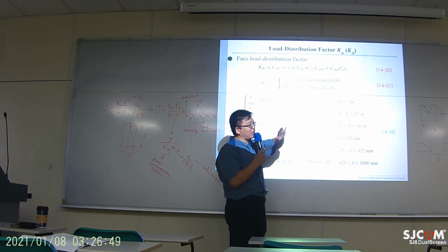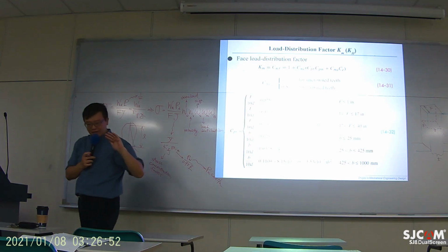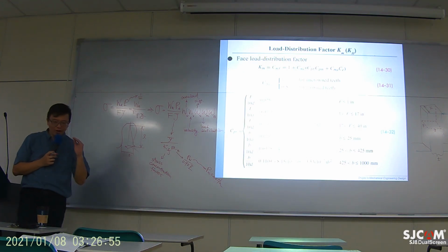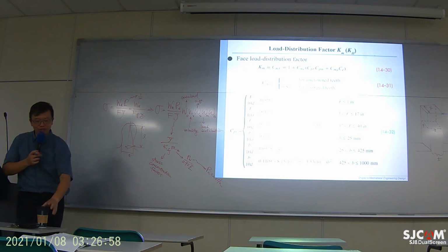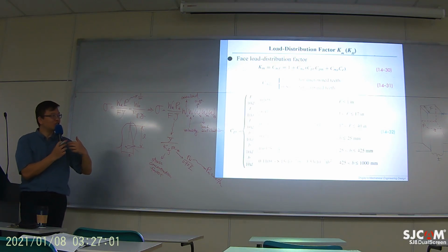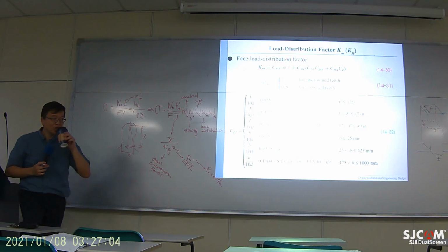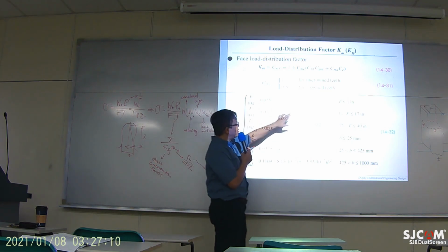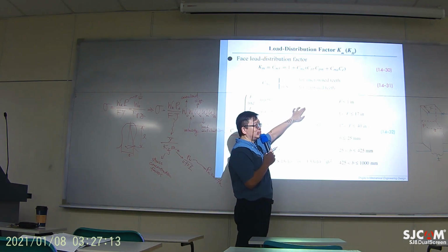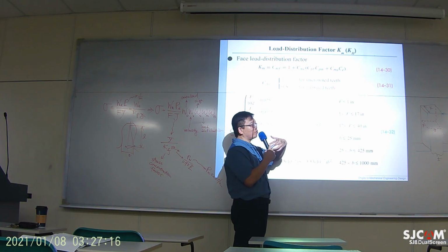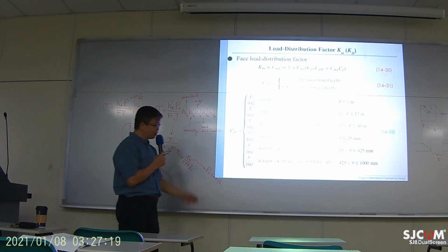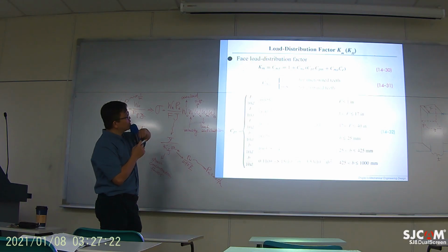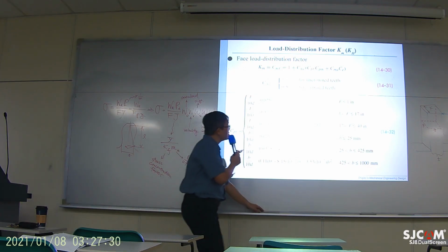Usually after machining, the edges of the gear teeth are sharper, so you kind of need to wear out the sharp corners. But if you crown your tooth, that will generate smoother operation between the mating gears. But you can see it's actually affecting this load distribution factor. Okay?